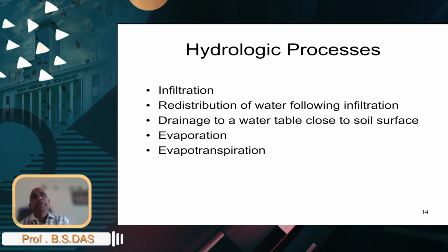Now, when you look at this field water balance equation that we talked about, we know that the storage change that takes place in a soil is a result of what? All these hydrologic processes, whether it's an irrigation water, whether it's a rainfall, water infiltrating across the soil surface, and water getting lost because of deep percolation or drainage, because of the evapotranspiration. Each one of those is a hydrologic event, right? And so you also saw in derivations of the Richards equation, we were looking at how the soil changes its soil wetness related to the fluxes of water coming in and going out.